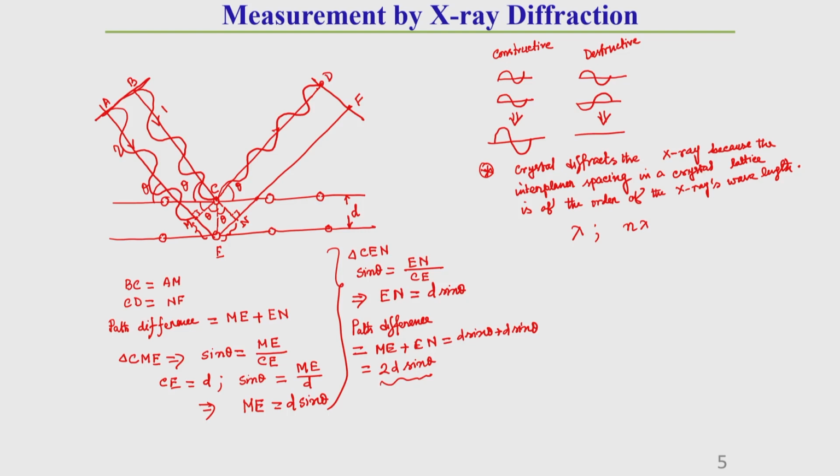Now, you see, to get this X-ray diffraction, what I have told you, and to get the detection of this X-ray by the detector, both the X-rays should be in the same phase, correct. So, this output X-ray also should be in the same phase with the first X-ray, correct. Then only here it will be a constructive type of diffraction result, correct. Then only here it will be constructive, because if it is opposite, your diffracted wave will not be detected by the detector. That means, in a destructive type of interference, X-rays of the same wavelength will vanish.